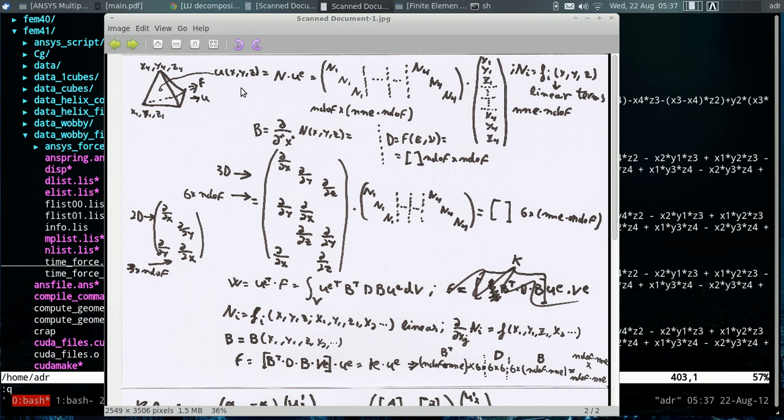And for that we may want to use a shape function which takes the displacements in any middle node in terms of the displacement of the corners of the nodes of this element. It will be the shape function, which will be in this case a 3 by 12 matrix, and the displacement is again a vector of 12 elements.